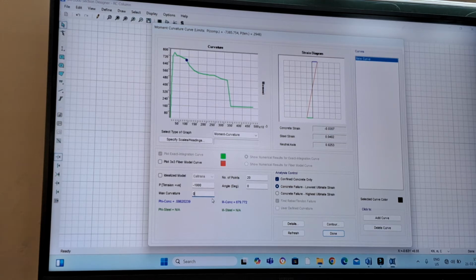So you understood, right? What moment curvature is and how it varies with respect to axial force in terms of stiffness, strength, and ductility. Now, same thing, you can take the same example, solve manually and compare with the software whether you are getting the same result or not. And now we will see in ETABS how we can do the same thing.